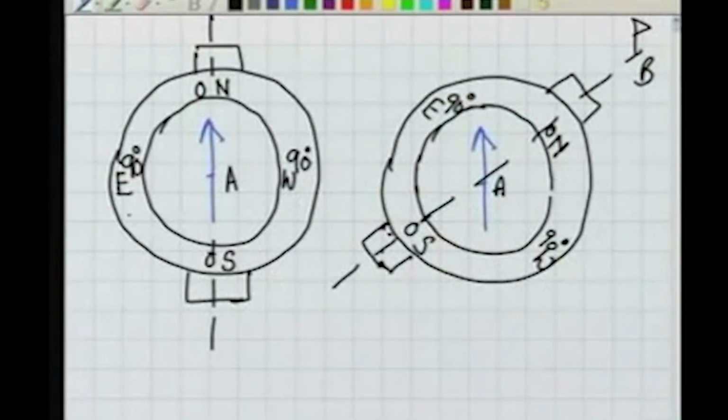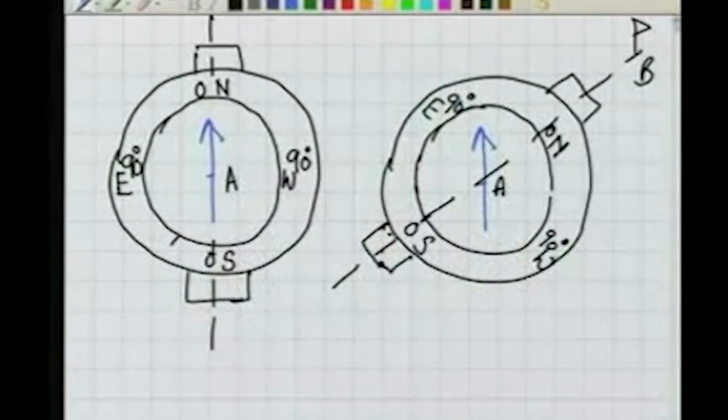Now in this case, all these black lines are the body of the compass. The interesting thing here is, along with the body, we also have the graduations. Unlike the prismatic compass, the graduations are in the body of the compass. In the prismatic compass, there was a ring of graduations and the needle was fixed to that.